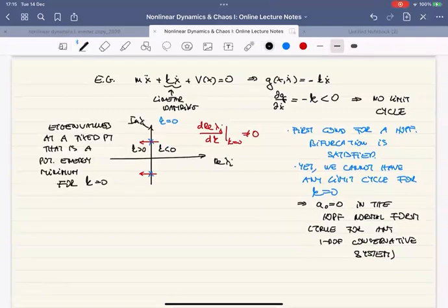I have a quick comment. I think there is an example of an external forcing which is only position dependent and still non-conservative, which is a follower force. I remember studying a course on stability of structures for a cantilever, for instance. If it is subjected to a compressive load and this load follows the axis of the beam, then this is a follower force, and I think this is path dependent.